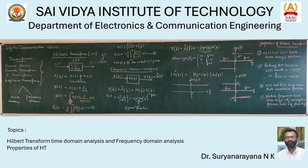Substitute and express this equation in the form of a convolution integral, that is given by integral from minus infinity to infinity x of tau into 1 by pi into t minus tau d tau. So simplifying, we are going to get the Hilbert transform of x of t, x cap of t, equal to 1 by pi integral from minus infinity to infinity x of tau by t minus tau d tau.